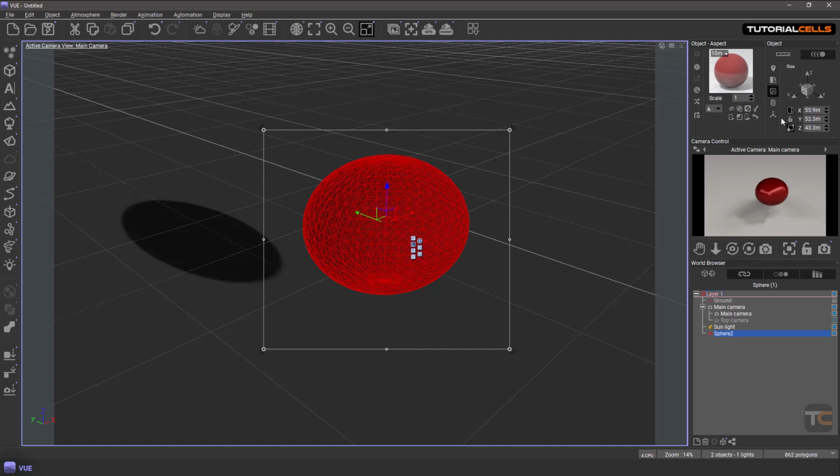And here, if you go to the scale, we have other tools. If you turn it off, you can display true object dimension in meters, or you can see it's not true. It's based relative to the object. It is better to use true object, because in a view, we are using the true dimensional object, for example, landscape.